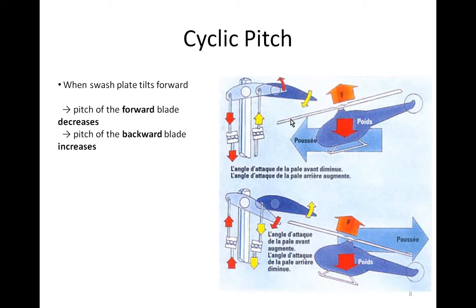On the front, lift decreases. On the rear, lift increases. So the front of the heli moves down and the rear moves up. The heli tilts forward.